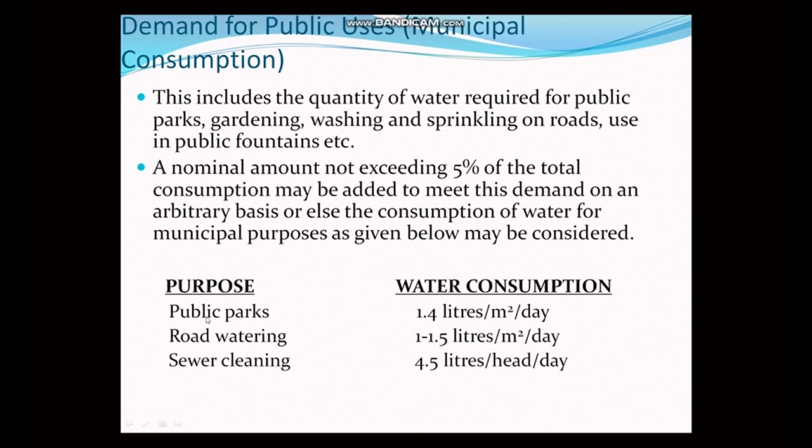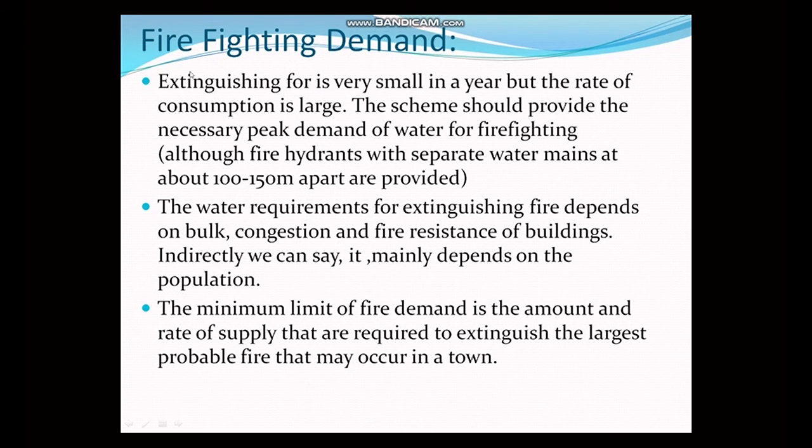For the purpose of public parks, the water consumption can be considered around 1.4 liters per meter square per day. For road watering, the water consumption can be considered as in between 1 to 1.5 liters per meter square per day. And for sewer cleaning purpose, the water consumption can be considered as 4.5 liters per head per day. Now let's come to the firefighting demand.